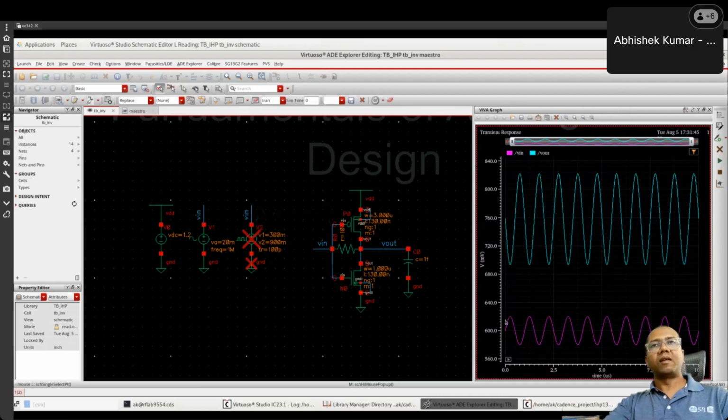And when we say it's an analog block, here you need to carefully see the value of the signal at all times. Here you see it's a specific periodic sinusoidal waveform where the value of the signal is important at all the time instants. And also you can see that these values are changing smoothly over time. Okay, there are no sudden jumps. This is the kind of signals we will be seeing in real life. It may not always be a sinusoid. It can be some other random signals, but it will be valid at all times, and the values will change smoothly.